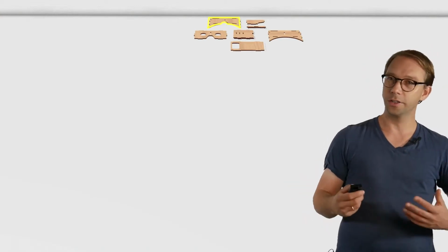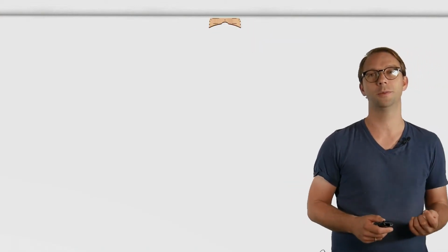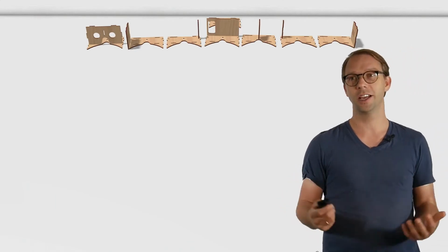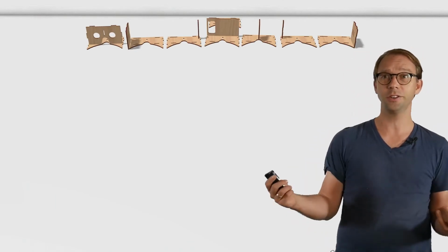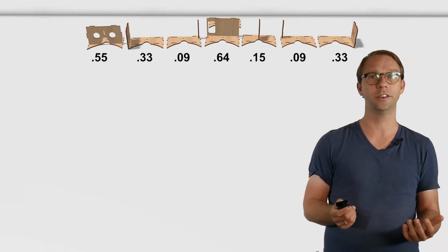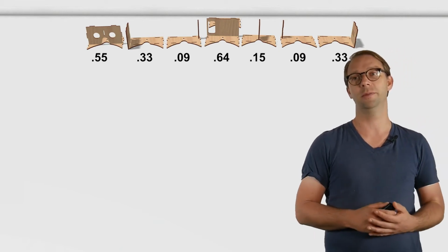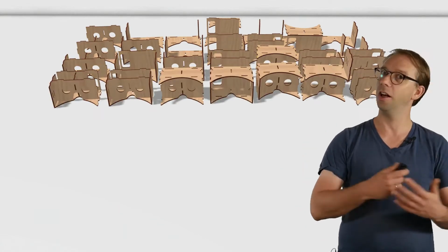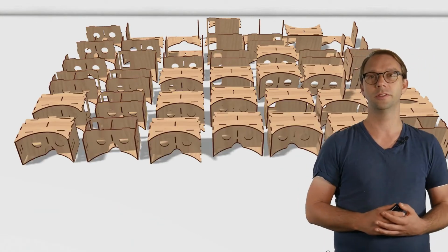Under the hood, AutoAssembler beam searches the space of possible assemblies. It starts with the plate with most joints and then assembles next plates into the model. It scores each of these assemblies based on its heuristic function and picks the 4 best assemblies. It then recursively executes this routine until all plates are assembled into the model.